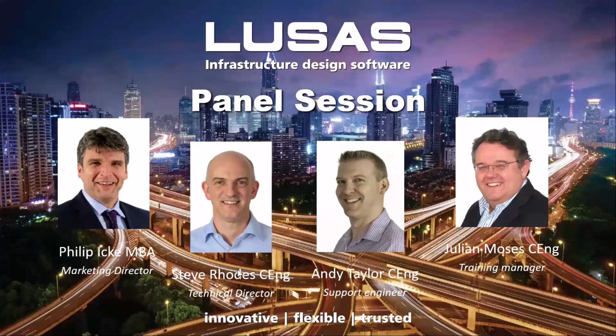Yeah, so I was just going to add, I think it's worth saying that we do have clients who use LUSAS for blast analysis and that sort of thing. So they are actively using that kind of concrete damage model together with other non-linear materials and so forth with that kind of dynamic loading. What you did was very reasonable. I think most bridge engineers would recognize a kind of pseudo-static equivalent to an impact load. The other thing I was going to add as an obvious damage and potential application of dynamics would be seismicity and then the damage on a structure from an earthquake. And similarly, you could calculate the cracking during the seismic event using our transient facility to do that.